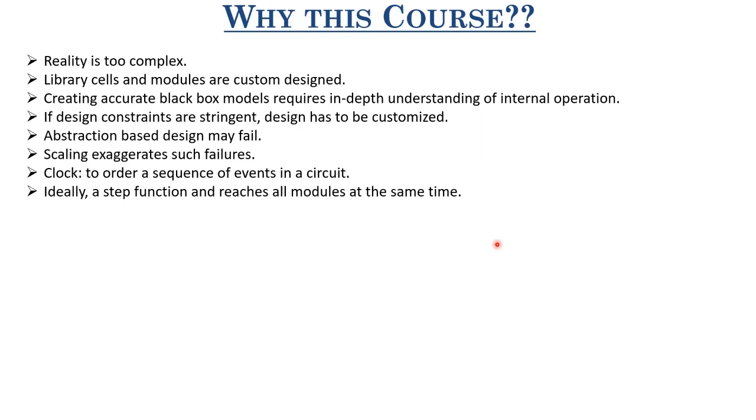And that is being hindered because of these parasitic capacitances, which are introduced because of scaling, as well as because of the components on a chip. The second problem that I discussed was power distribution. All of these modules are connected to the same power supply, right? And the current and the voltage given by that power supply should be stable over time.